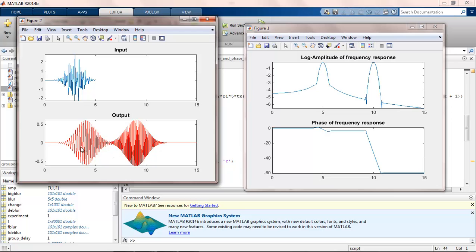Okay, notice it's exactly what we said. You get 2 sinusoids out. The 7 got eliminated, and the 5 frequency gets delayed a little because the slope's only a little. The 10 frequency gets delayed a lot. So magically we see this group delay coming to life here. I can justify to you in the next lecture why this group delay works this way.